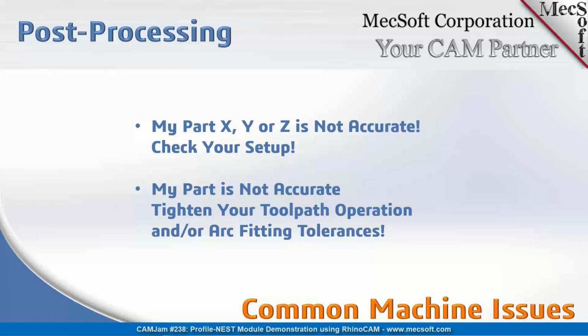If you have one of those controllers and you see some weird things going on, arcs going off in space, and this is obviously something's wrong, go back into your RhinoCam file, your Visual CAD CAM file, and double check your accuracy in your machining operation dialog. Check your global accuracy and also your arc fitting.